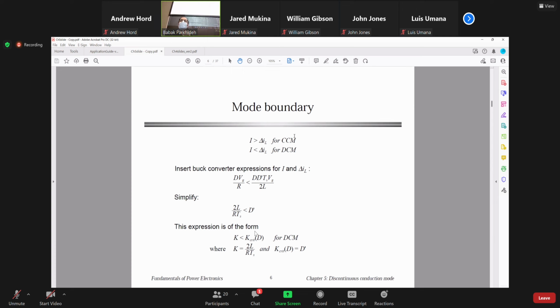And when the load current is smaller, you are in a DCM. So now, depending on what type of converter you have, you can find a relationship for the average current in the inductor and the ripple, and see if you can find any parameter that you can extend to all kinds of converters. That's not needed, but for basic converters it is possible.